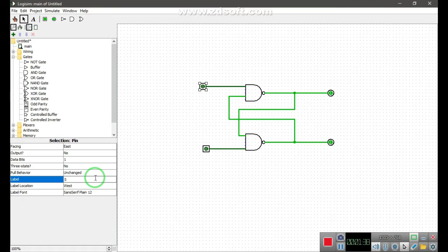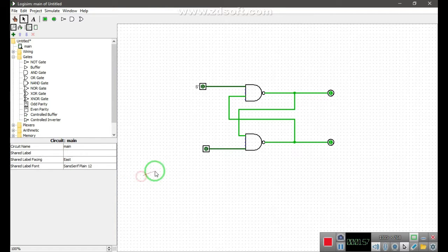Since one of these inputs is still at logic level 0, the output at Q still remains high at logic level 1 and there is no change of state. Therefore the flip-flop circuit is said to be latched or set, with Q equal to 1 and not Q equal to 0. Now the reset state.